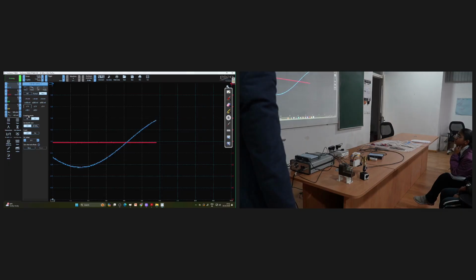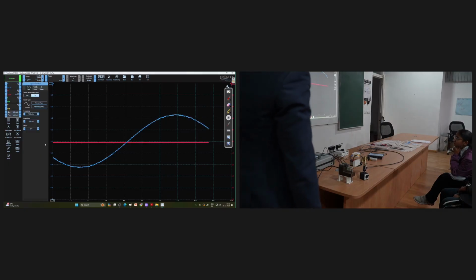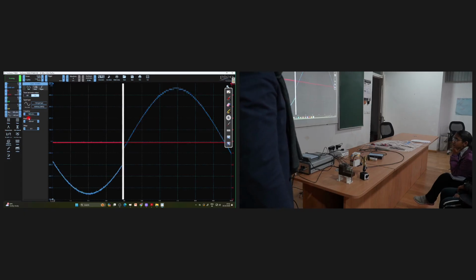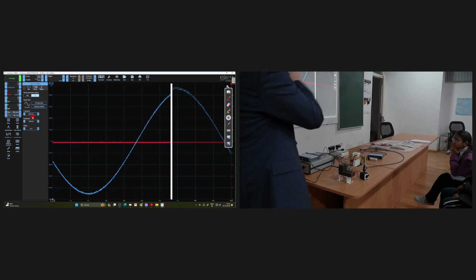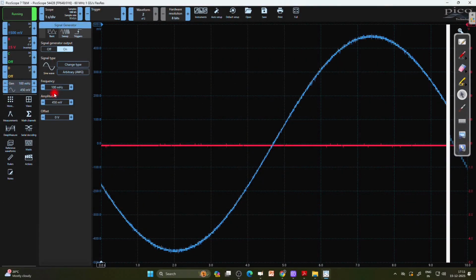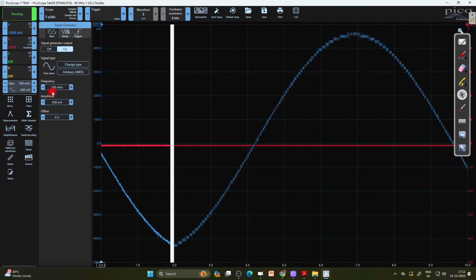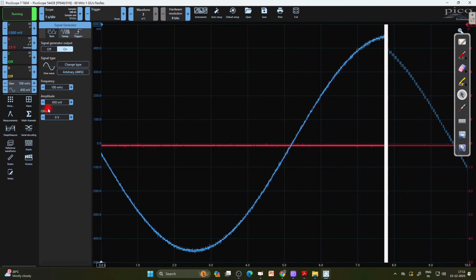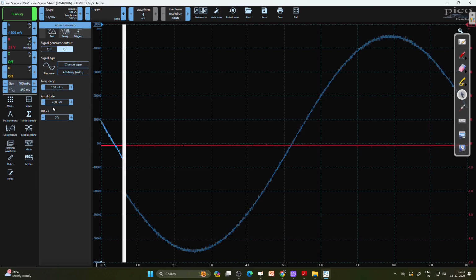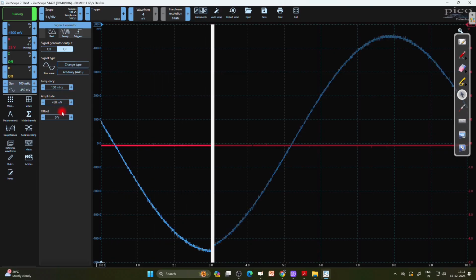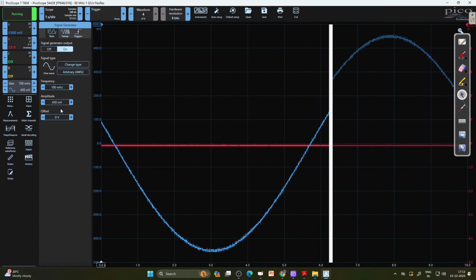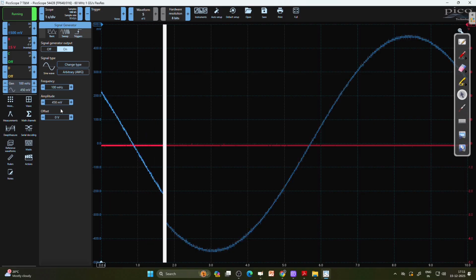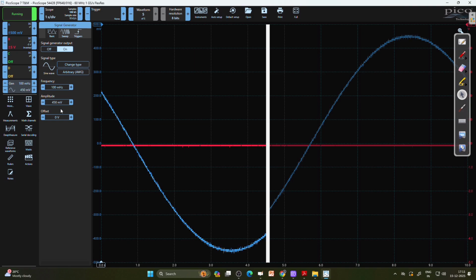Yep. What I prepared is, I used a very small frequency of 100 millihertz, not megahertz, millihertz, so 0.1 hertz. So very slowly, we increase the voltage, we decrease the voltage, and we shift between minus 450 and plus 450 millivolts. So that's the amplitude, right? This is what you can now see, since I connected the signal generator output to the input channel A. You can see on channel A what the function generator outputs. And on channel B, you just see what the laser distance measures.